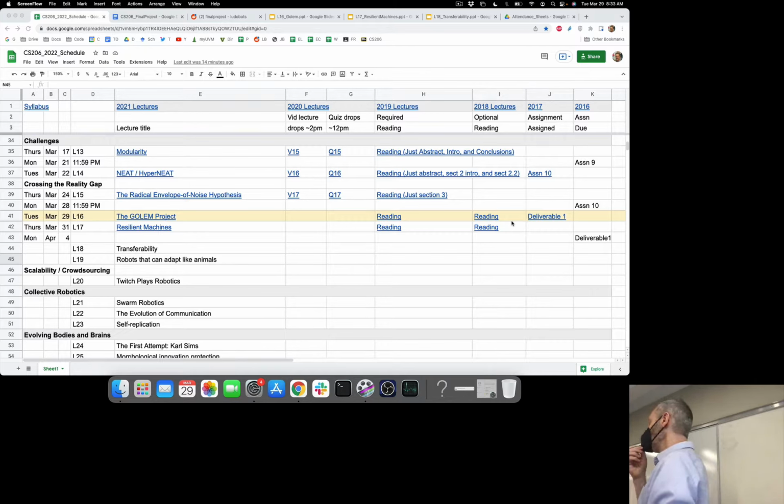Some of you have already, I think, come up against the limits of your device. If you're running a population size of 10 for 10 generations using the quadruped, there is usually a pretty considerable memory requirement for that. Each individual simulation obviously has a larger number of links and joints and all sorts of things going on. So PyBullet, the physics engine that is underneath PyroSim, it will allocate more memory the larger and more complex you make your robot and its environment. So that takes up a fair bit of memory. And then, of course, you have 10 simulations running in parallel. And I saw some students in my office hours this week, and it was clearly too much for their laptop.